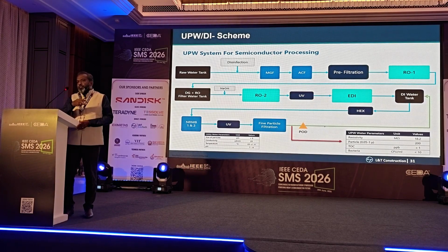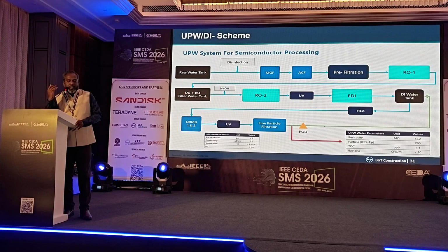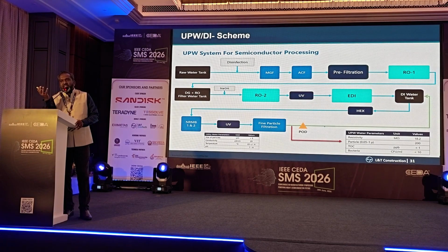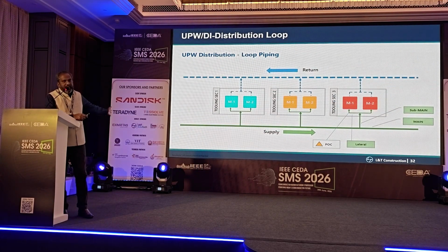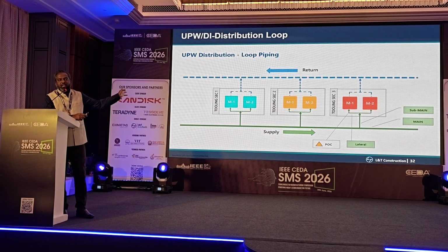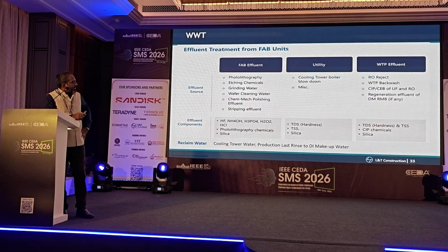So we have a lot of filtration processes. One process before UPW is DI water. In most industries we use demineralized and DI water. So that is one process. So what happens on the supply? You have ultra pure water in the supply that goes to the tools, and then this water is not thrown out. This goes back to the DI tank. If I go back,